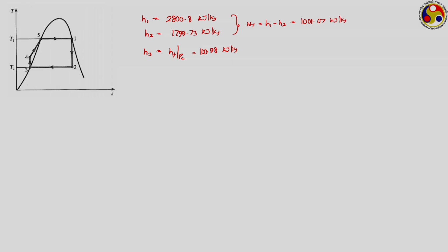So, the turbine work remains the same on adoption of the Rankine cycle, but what about the pump work? The pump work definitely will be changing. So, let us try to calculate the pump work. The pump work in this case will be equal to the corresponding specific volume into the boiler pressure minus condenser pressure. Now, check the value of this specific volume. Let us say it is V3. V3 will be equal to V4, which is equal to Vf corresponding to the condenser pressure. These two should be very nearly equal to each other, and if you put the values, you will get something like 0.001 meter cube per kg, an extremely small number. V3 and V4 remain virtually the same, and putting that we get the pump work to be equal to 39.97. So, the pump work is coming as 39.97.